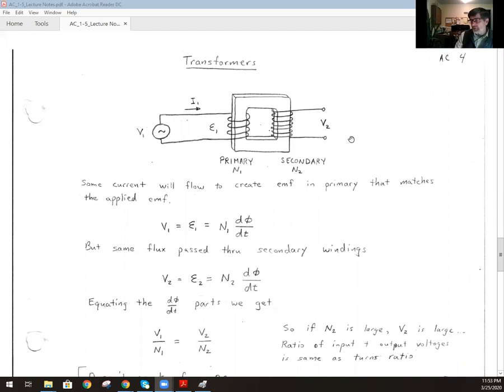You put them together a couple different ways, and you hooked up a power supply that was plugged into the wall, but it was outputting AC. So you were feeding an AC waveform into the transformer, and then looking at the AC waveform at the output of the transformer, and then you connected it up with a light bulb and switched it on and off and did various things like that. And you also rearranged the transformer. The crucial thing in a transformer is the turns ratio. How many turns, how many coils do you have in the secondary, and how many are there in the primary?